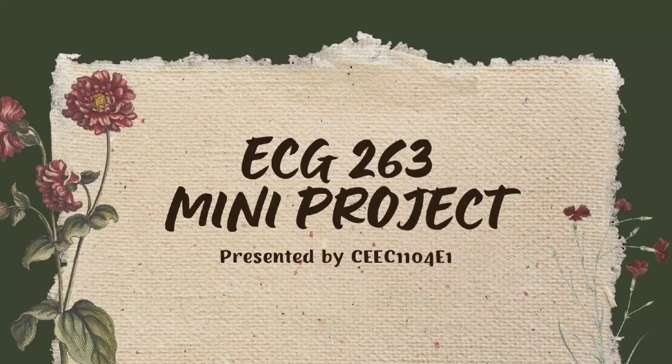During our test, we took careful steps to get accurate results. For example, in the field density test, we inserted the core cutter gently to avoid disturbing the soil. However, we used some improvised equipment which might have caused small errors in our measurements.